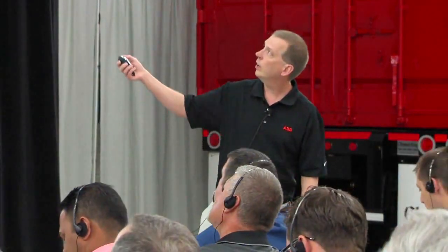Back here, when we talked about a stop command, when you open that switch, the drive can ramp to stop, which means that you can bring it down on a controlled ramp at whatever rate you want. If you want it to take 30 seconds to stop, that's fine. Maybe that avoids some mechanical stresses on your system by having a long ramp rate.